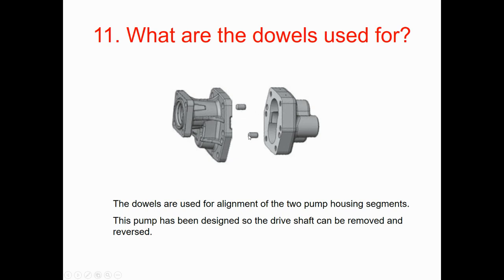Just imagine that if we don't have this, we need to find the location of the hole here, for example. If I would like to insert the bolt, I need to keep looking for the threaded hole through the cap hole, and this will take some time. We usually try to reduce the time for assembly, so putting in the dowel is going to reduce this time.